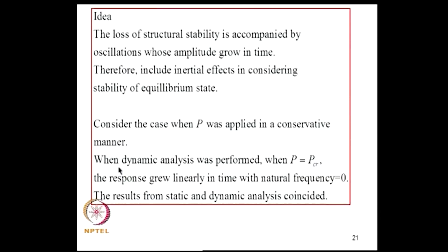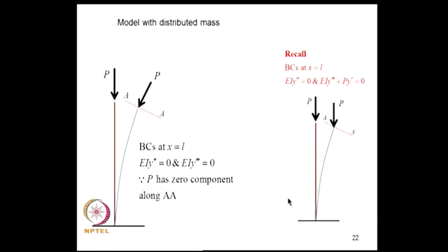That means the direction of P would remain unaltered due to deformation of the structure. So, when dynamic analysis was performed and when P equals P critical, the response grew linearly in time when the natural frequency was 0. The result from static and dynamic analysis coincided. Okay. So, this we can recall in this context.